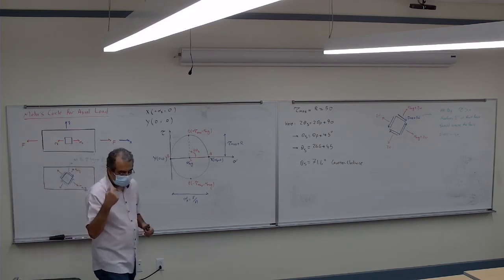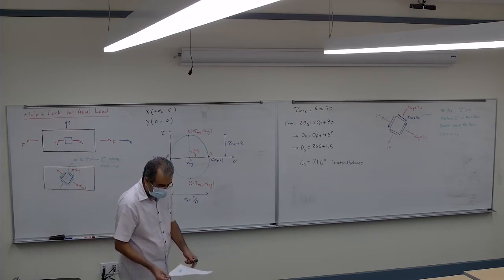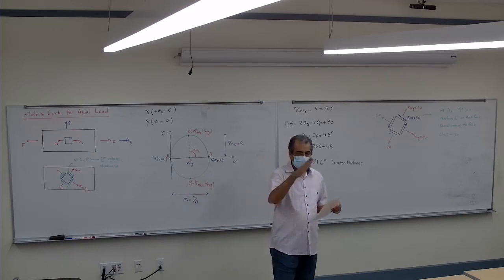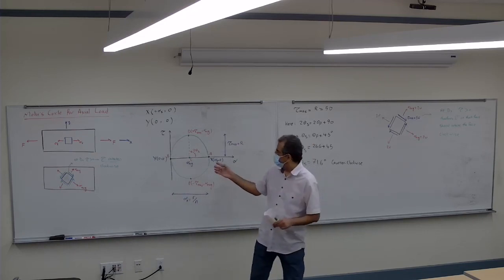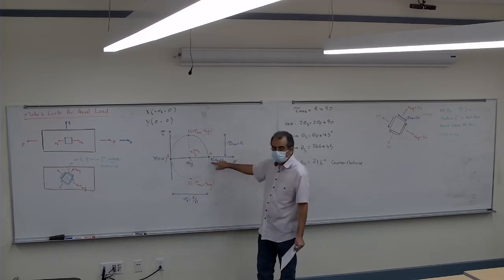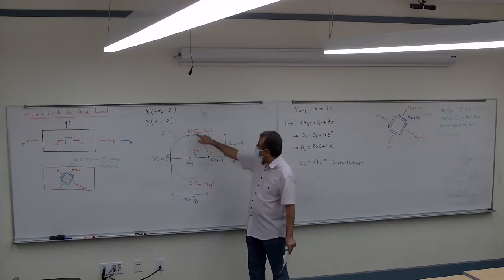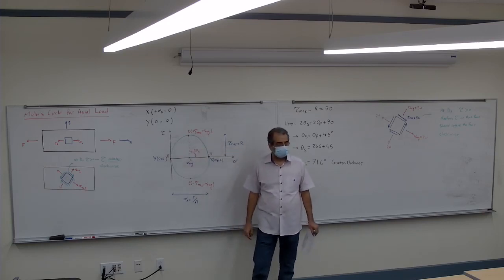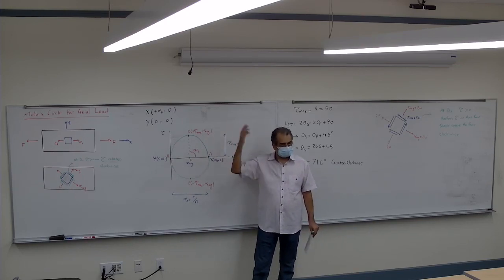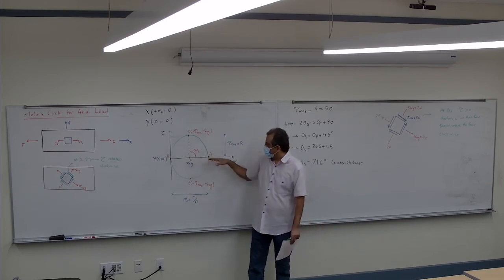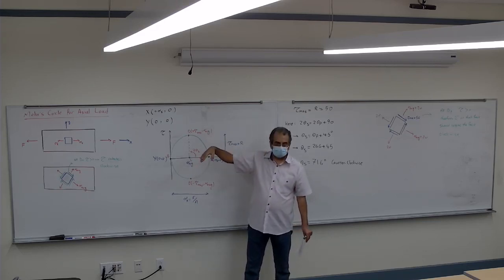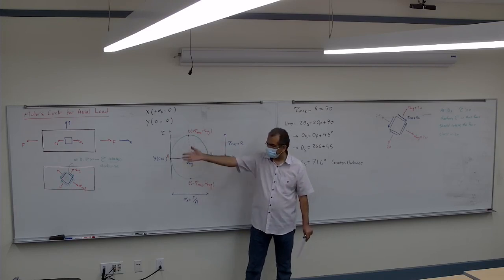So I can remember at the very first chapter we talked about it that says that there's 45 degrees between the maximum normal stress and shear stress if we have only axial load. Remember the very first chapter we talked about the axial load. It says that wherever we have the maximum shear stress, if we rotate it 45 degrees, it's going to be maximum shear, and that's why.